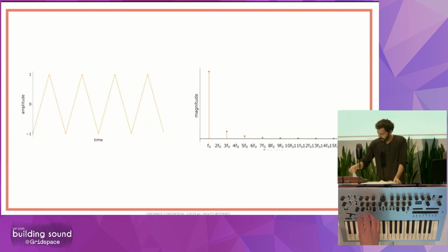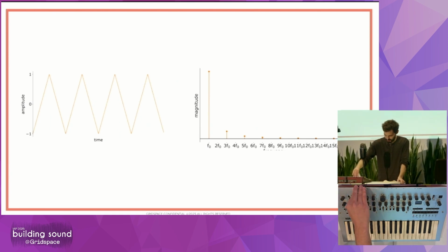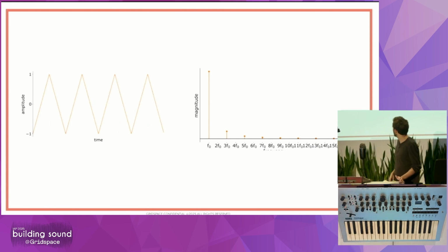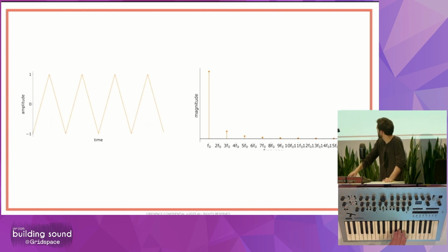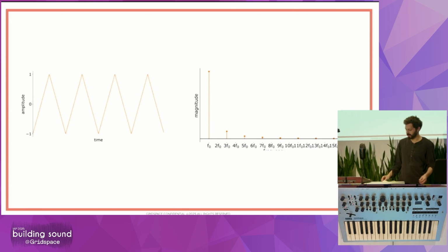And then the last shape of the oscillators are triangle waves, which by their shape sound a little bit like sine waves. You can see it's the same as the square wave, where it's only got the odd harmonics, but they're reducing a lot faster, right? So in the harmonic diagram, it looks a lot like a sine wave. It's just got a little bit more of those overtones to it. And as a result, it has that smooth, kind of video gamey sound.